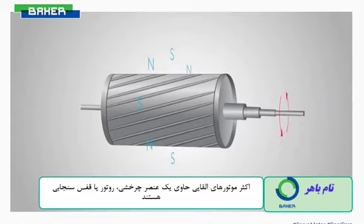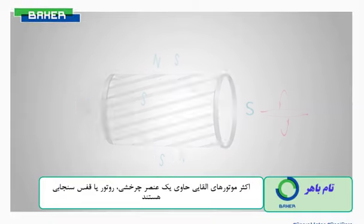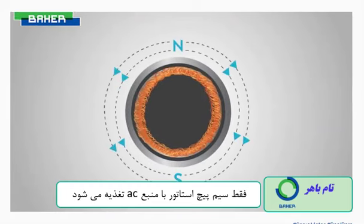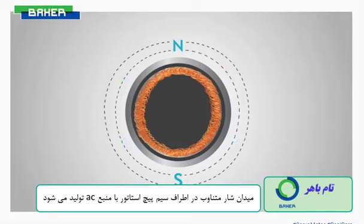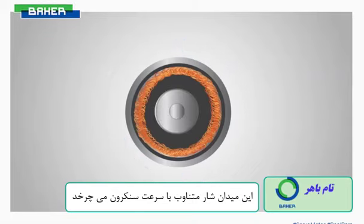Most induction motors contain a rotational element, the rotor or squirrel cage. Only the stator winding is fed with an AC supply. Alternating flux field is produced around the stator winding with the AC supply. This alternating flux field revolves with synchronous speed.